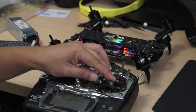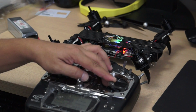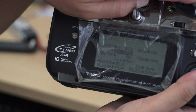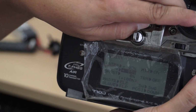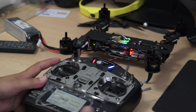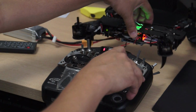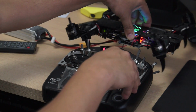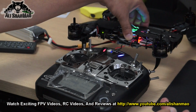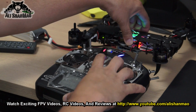Alright, similarly I will do it for the rear. I will move the elevator all the way back, and then I will change the values. So for me, 85% is working perfectly, and now you can see my dynamic rotor tilting is working. If I want, I can simply turn it off by using the switch G that I have just set.